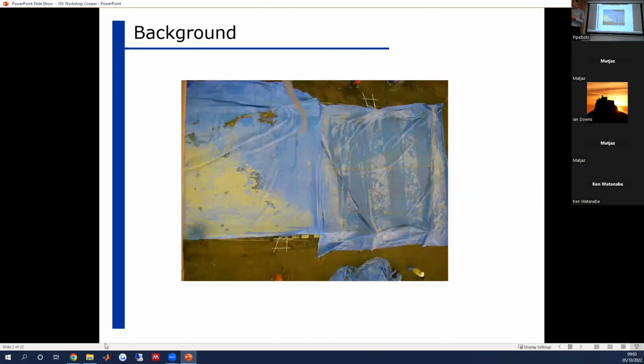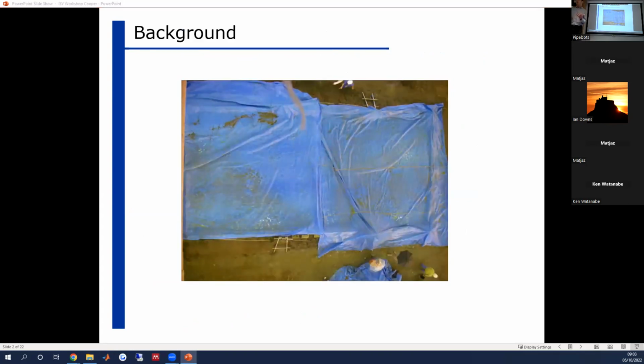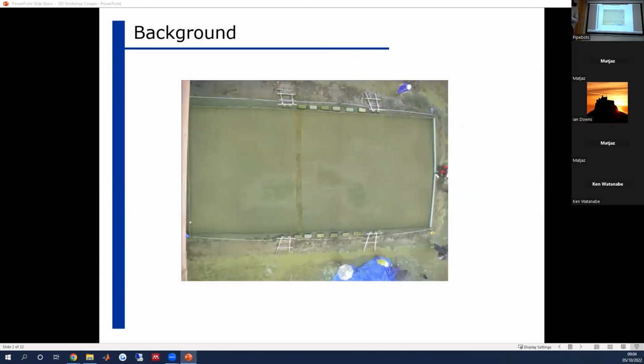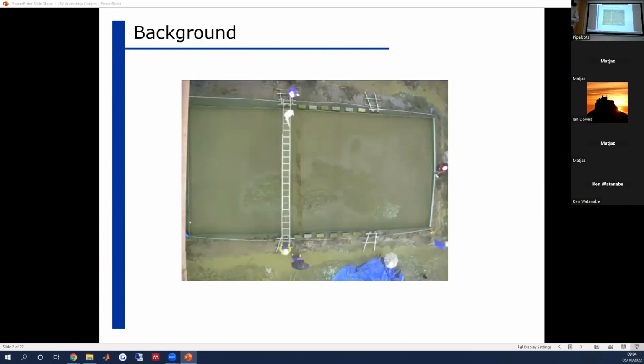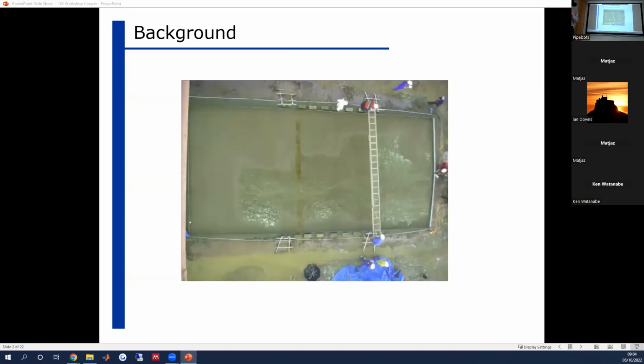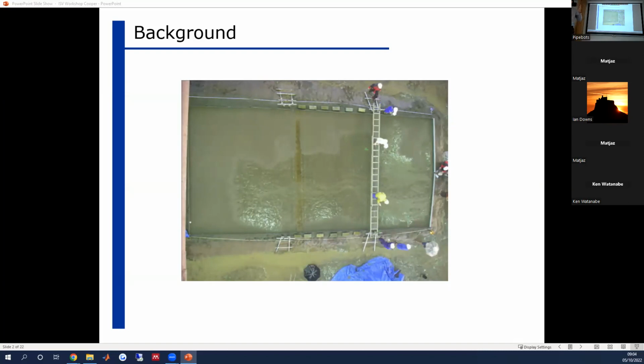This is a video showing some rainfall simulation experiments that we've been doing in Japan, where you'll see that this plot is going to be exposed to a pretty extreme rainfall event, a duration of 20 minutes and a high rainfall intensity of 120 millimeters per hour. This is the kind of problem we're trying to address: how can we understand the dynamics of these flows? Very early on in that video, you'll see the development of Hortonian overland flow. That flow area of inundation then expands through time.